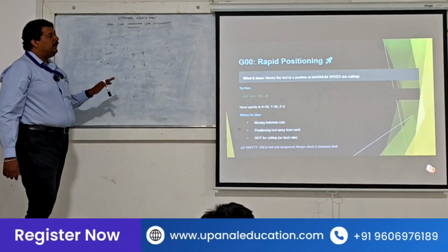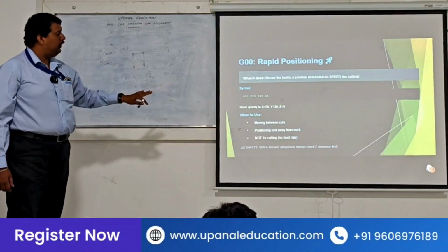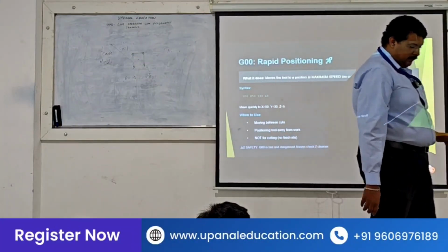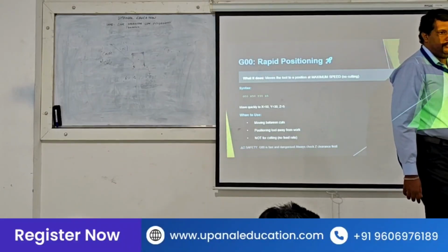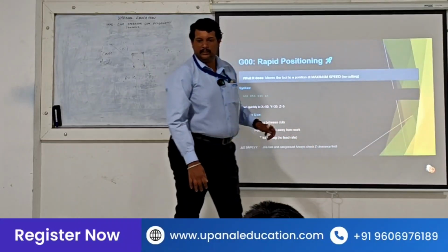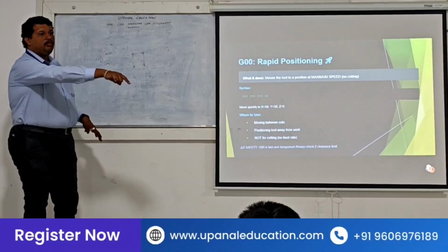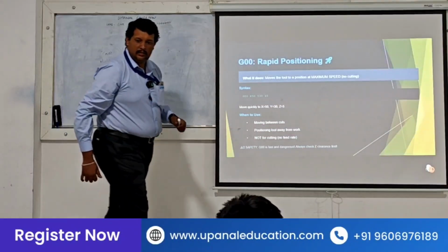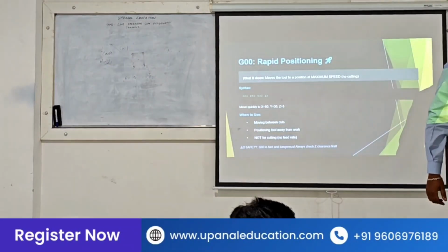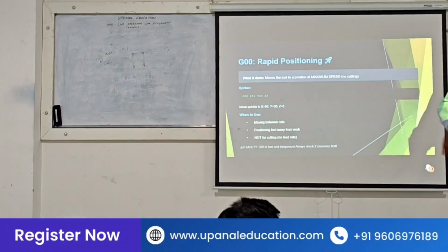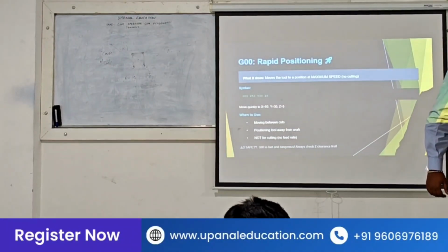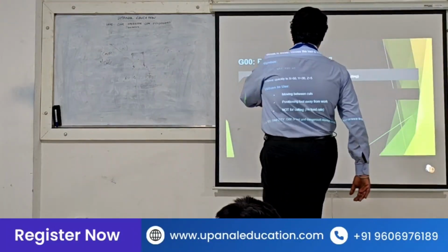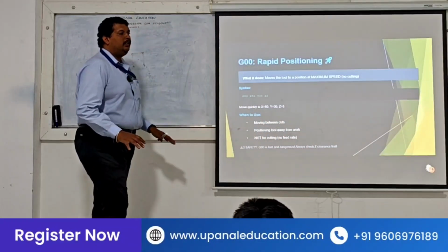That is rapid positioning. For example, this place is my X50, Y50, and my machine 0 is here. I have to work there, so I want to come fast. We go directly fast, but there is no cutting or anything. I'm just coming here in height. From here I will go with the next line. So with G00, we are just telling it to go quickly to that position.